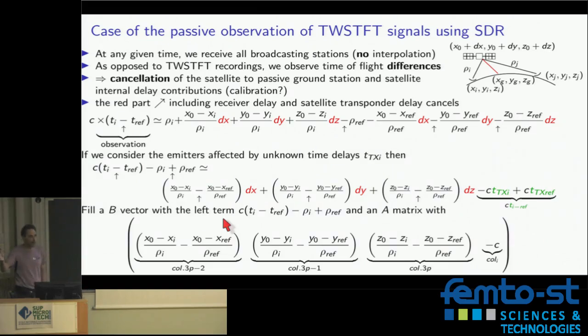They take the BIPM data, they do all their fancy signal processing, and they say, look, I find a nanosecond. Yeah, but in real life, you're not going to have a 2.4-meter dish. You will not have an atomic clock. You will have a shitty TCXO running an SDR on a 60-centimeter dish. Well, what do we get in real life?